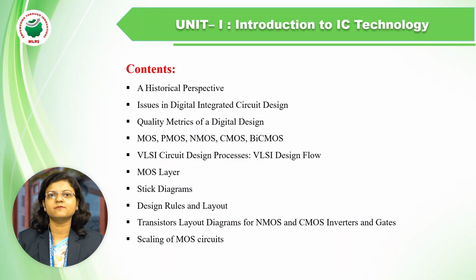MOS layers, stick diagrams, which is the cartoon of the layout, meaning whenever the designer wants to design the layout of the circuit, he has to first go through the stick diagrams. How to draw the stick diagrams, that we are going to see in the first unit. After that, for layout designing, some design rules we have to consider. Some lambda based rules and micron rules are there for designing purposes, that we are going to see here. After that we will see NMOS and CMOS transistor layout diagrams, in which we are going to see the inverter layout, NAND layout and NOR layout, and some gates also. And the last topic in unit 1 is scaling of MOS circuits.